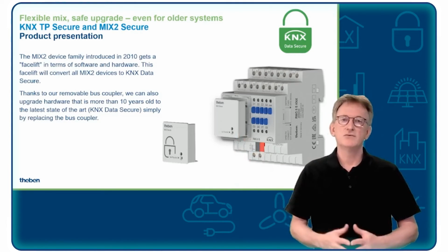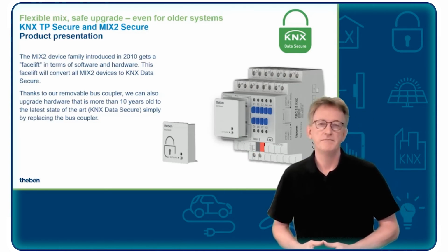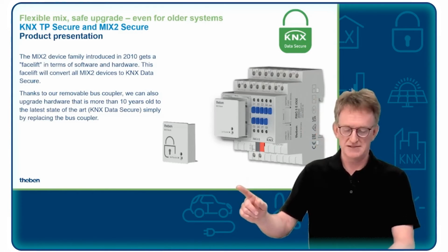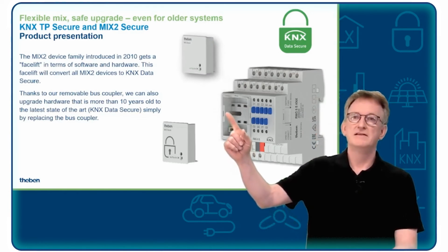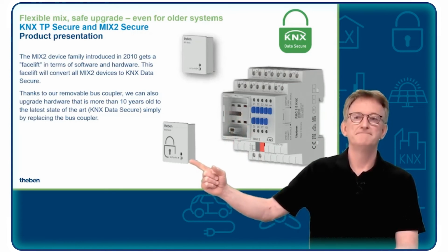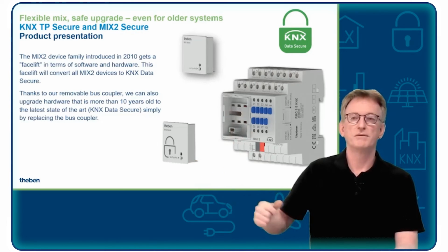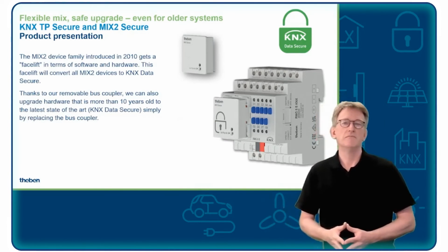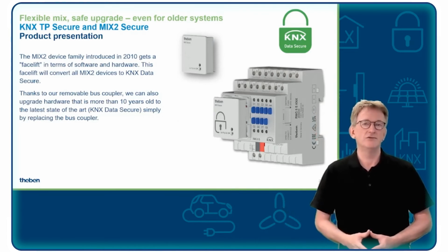So this old device you can directly migrate from the old unsecure version to a new one. How does it work? You just disconnect the old BCU from it, you order a new one from Theben and reprogram it and plug it into the device, and now your KNX device is a secure device.